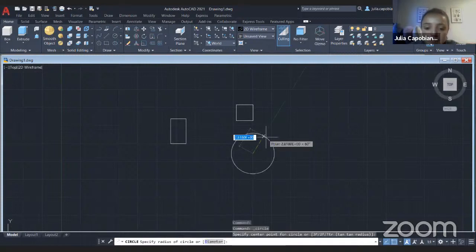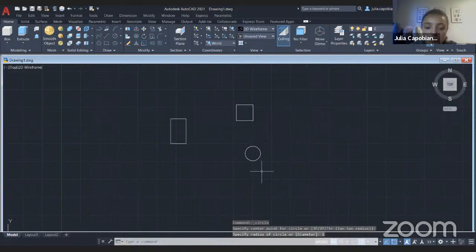But when you type this value into the little white bar right here, it's gonna represent the radius, not the diameter. So keep that in mind if you're ever designing stuff, because sometimes even I've messed that up. You could just type in 1 and you can see it makes a little circle. So that's also pretty easy.